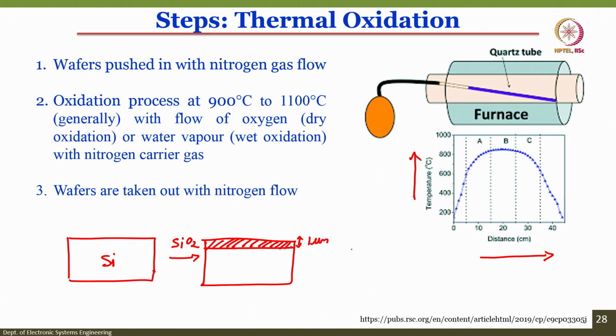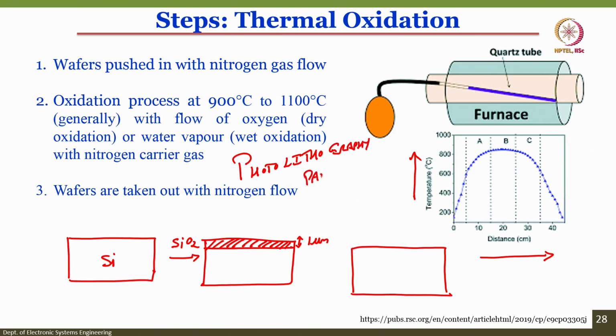So, for that you need to create a step, and I will teach you something called photolithography, which will help to pattern the material of your choice. Now, we want to create a step, that means using photolithography I will etch silicon dioxide from this region, you can see here. So, I will use photolithography to pattern silicon dioxide in the way I have drawn in this schematic.